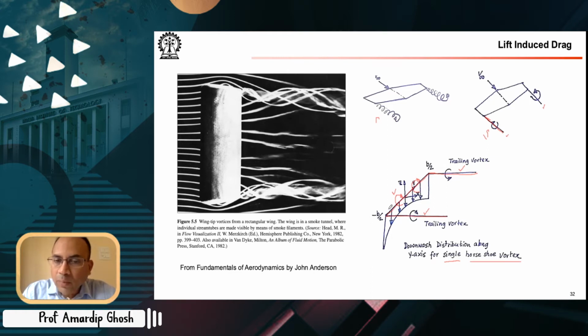And if you want to precisely model it, you will see that the circulation at these tips goes to zero because there is no pressure difference. So for this model, my circulation is constant up to the edges, and then the circulation is contained in these lines. However, in real, more appropriate models, our lift at the edges becomes zero because there's a way for pressure to communicate from the top and bottom surfaces.